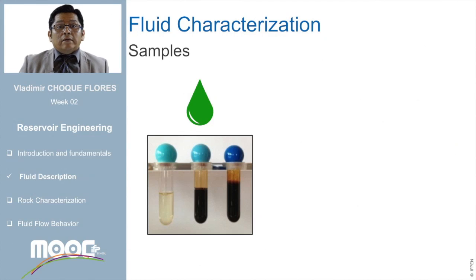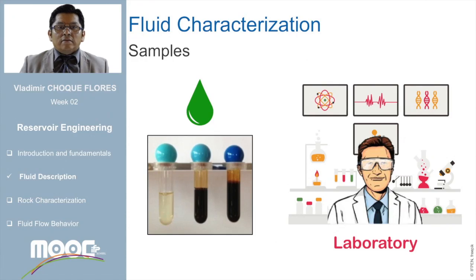In order to characterize the reservoir fluid, quality-checked samples are taken in the exploration and appraisal wells. Once the fluid samples are validated with quality-check indicators, some specific tests are performed in a specialized laboratory to determine the fluid composition, the saturation pressure, and the phase diagram, which I will explain on the next slide. Properties such as viscosity, density, and specific gravity are defined as well.